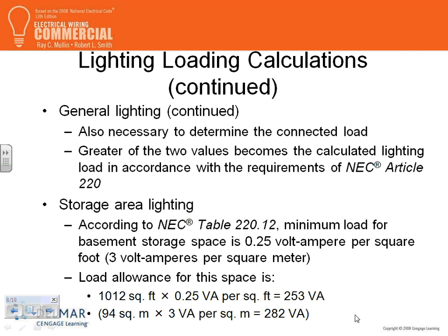Here's one thing I didn't do on my sheet, and they're doing it, guys. They're taking the storage area. If you go to table 220.12, the storage area, you find the volt-ampere for storage area is 0.25. What they're doing, Brad, is slicing the building into storage area, into a drugstore, into an office. That's how you should do it. If you have an area, you should slice it.